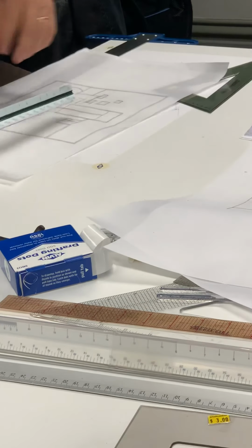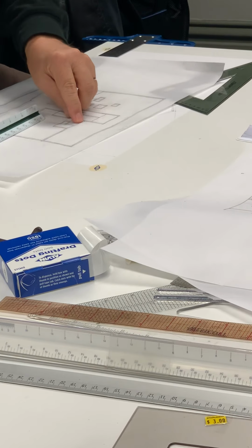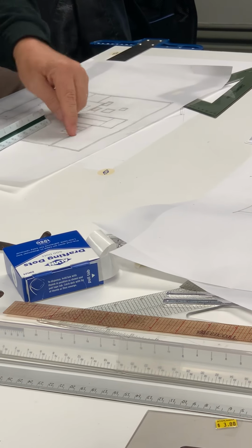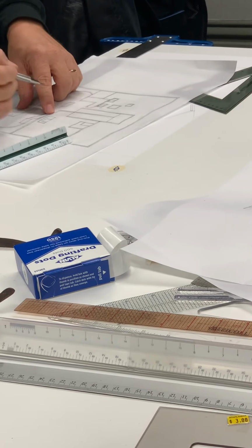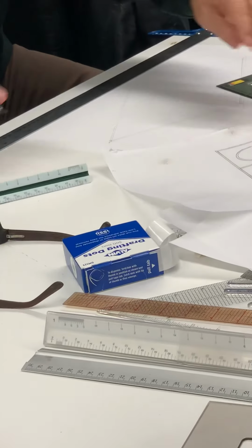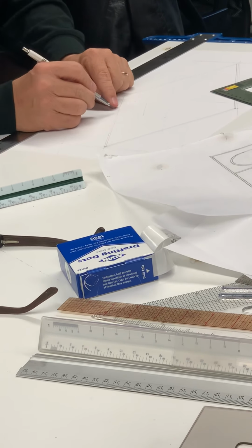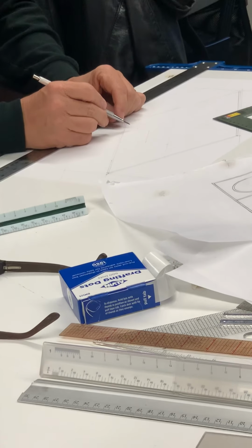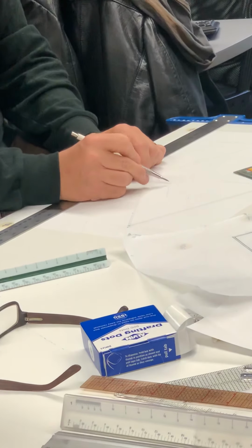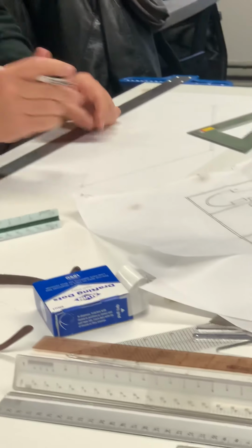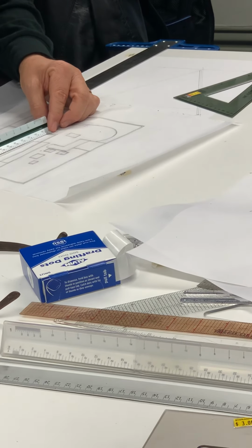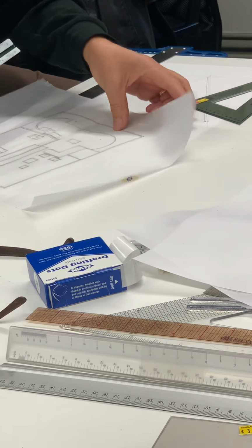So now I can see that point, right? So I'm going to want to go from that point to here. I can't really see this stuff here. So I have to draw it all from that point and all from this point, and then I find and locate that point and find this one. So now how do I do that one over here? What I might end up having to do is draw dashed lines for the hidden spot as to where that other line would be, right? Now I can find it pretty easily because all I have to do is know the dimension, and that's 27.